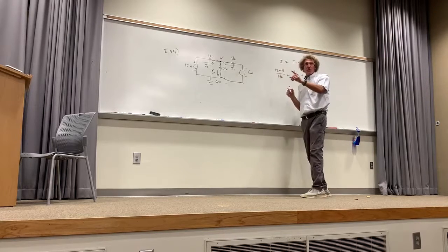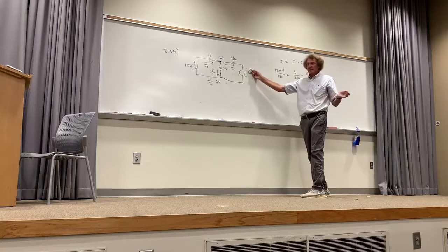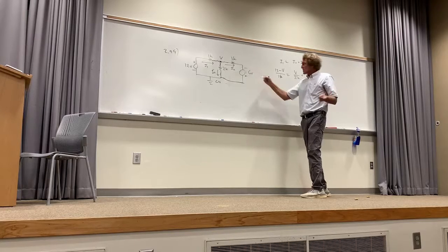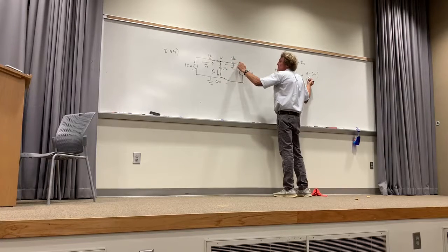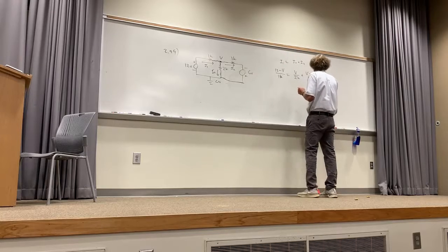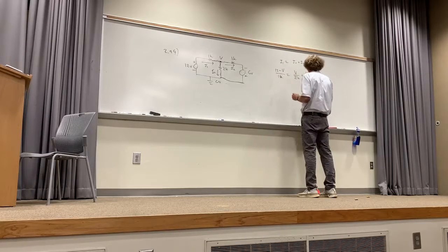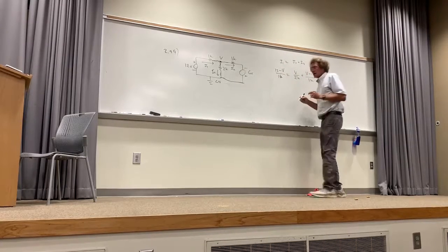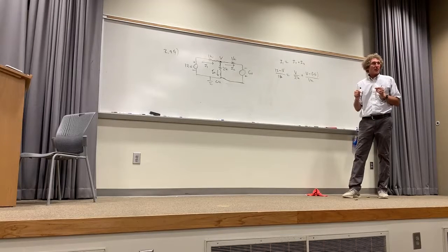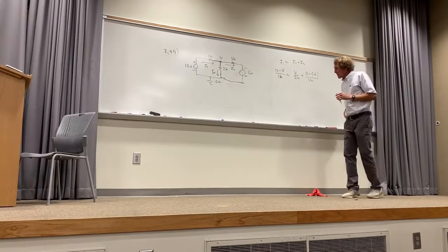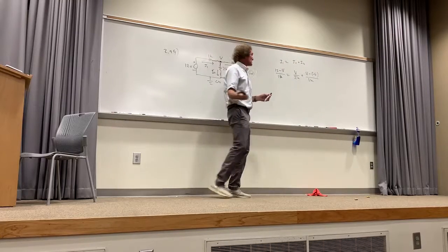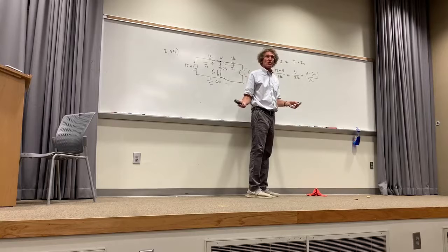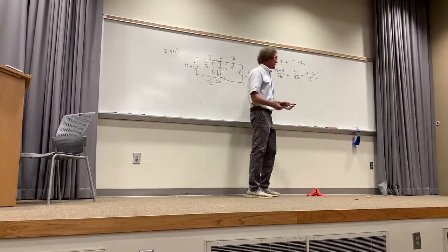Let's do it that way if you don't mind, because that's minus, right? The minus sign first. So V is the voltage on the positive side where the current's entering, minus minus 6 is the voltage on the negative side. So it's V minus a minus 6 over 1K. Correct, class? We're going to solve this. Y'all agree with me so far? Yes. All right, now, this is what I do. When I see something like this, you see K on both sides, don't you, class? 1 over K, I should say. Yes. Multiply by K and get rid of it.